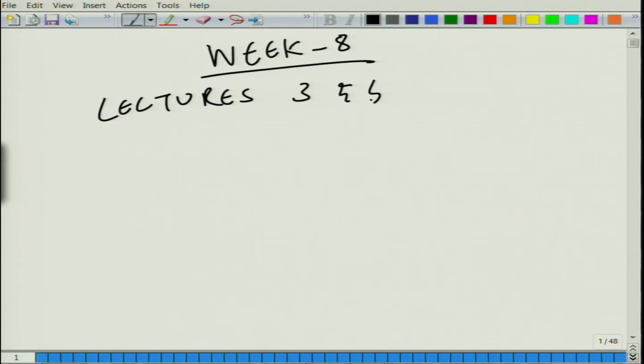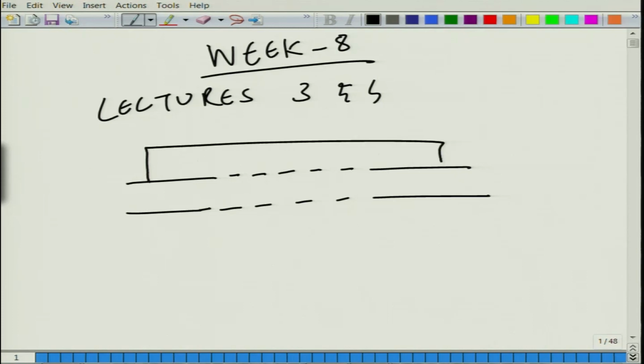So, basically what we were just about to solve was this muffler configuration, which is quite famous, quite popular because of its low back pressure, or minimal pressure drop across its length, across the points 1 and 2, the inlet and outlet points. And here this part is your perforated section.